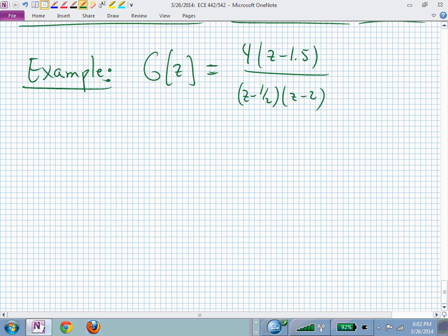So what are you going to do? What can you tell the interviewer about this plant to show that you have a little bit of insight into what's going on here? It's unstable, isn't it? In the open loop. If you just kick this guy, he's going to go unbounded. So one is you have a system that's unstable.